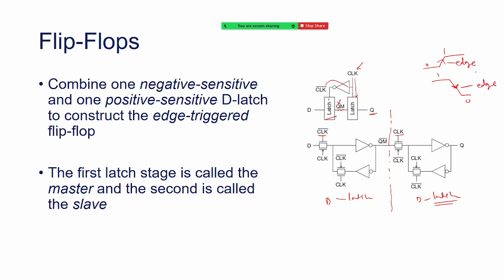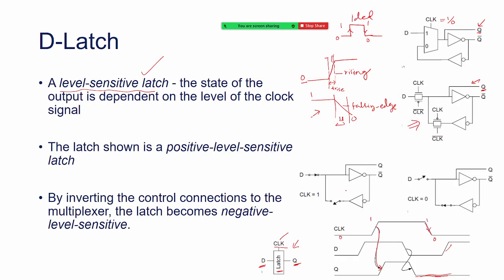So when you do the RTL coding and when you do the ModelSim simulation, when you use the compiler, then you will have waveforms like we are showing here. These waveforms will come to you. You will see the clock, then the input and the output of the circuit, and you have to interpret these waveforms: at what transition of the clock, whether it is passing from 0 to 1 or 1 to 0, how the data input is changing and how the output of the circuit is changing.